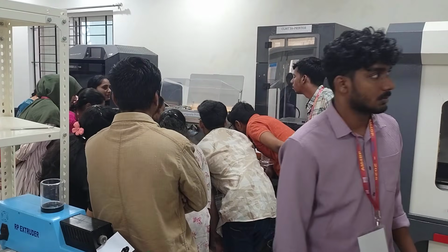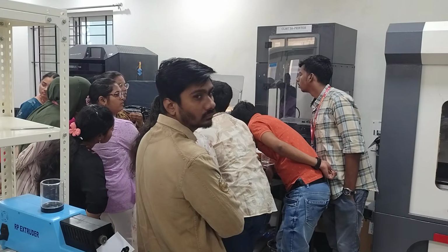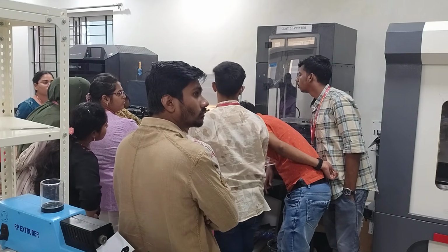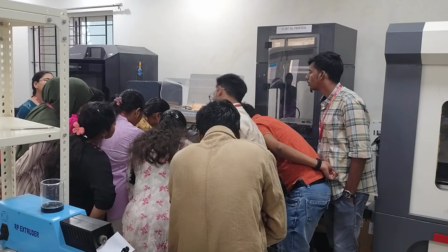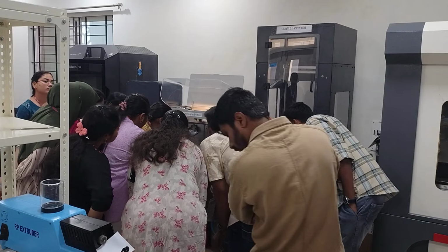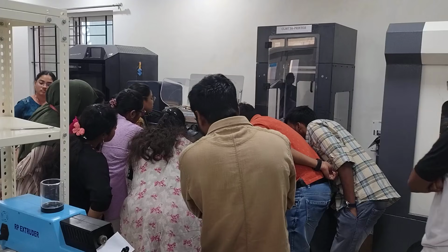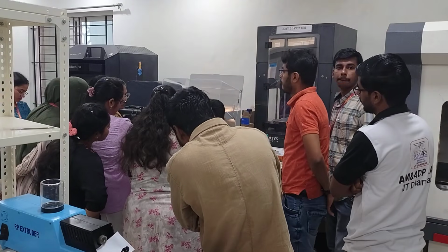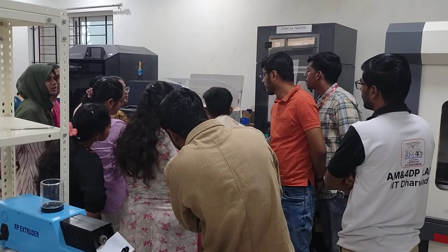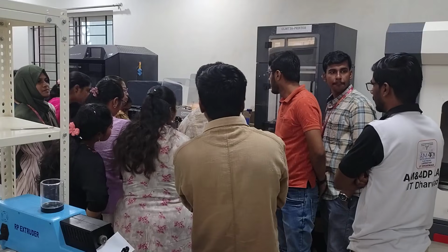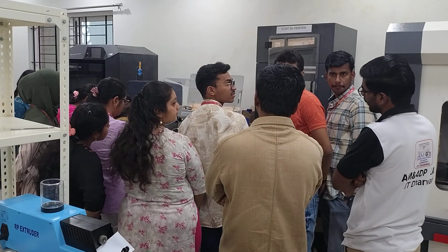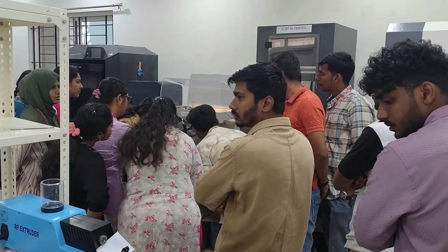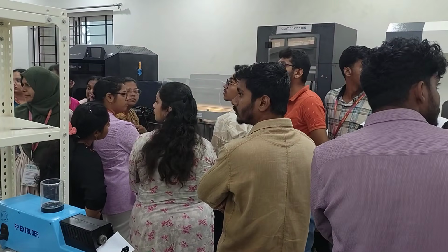Yes. Sir, so there are 3 layers of carbon fiber. So now the filament is getting deposited. So 2 layers, the filaments will be deposited. Thereafter we'll have a gap over on the wings after 5 layers of fiber, this matrix, and then again the filament will be deposited.